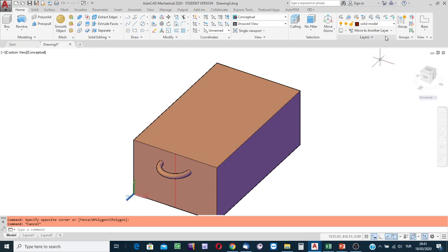Well, select the construction layer. I'm going to create a line extending from the midpoint of the top side boundary of the top side surface to its opposite boundary midpoint. To create the line over the surface, I'm going to coincide the XY plane of the coordinate system with the top side surface of this prism.